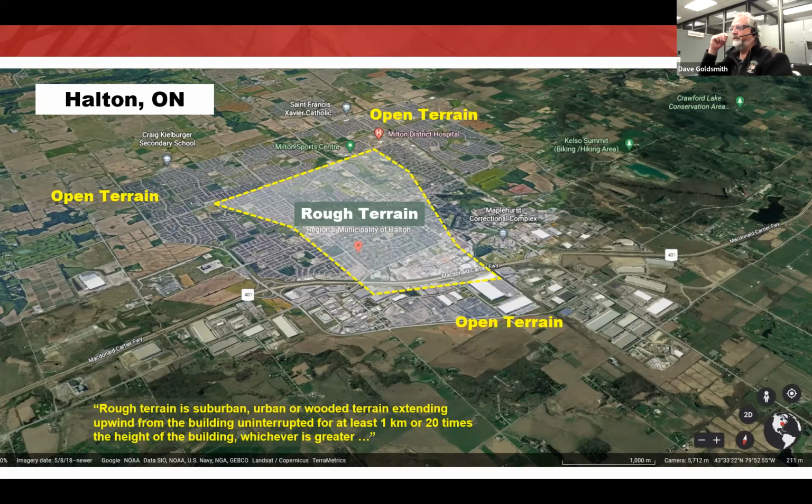No, we like to operate on the assumption of open terrain. And when it's in an area that has relatively low 150 hourly wind pressures, using that default gives you a reasonable required performance that your standard default windows will generally have. And many manufacturers, someone mentioned, Sudhir Sharma mentioned glass thickness. A lot of manufacturers, their default glass thicknesses are based on open terrain in an area,